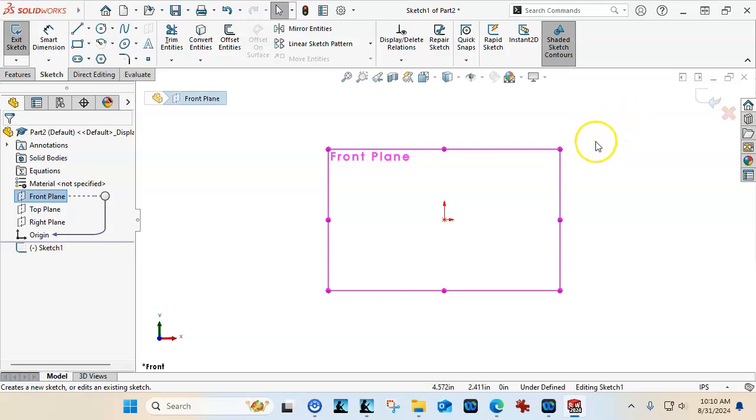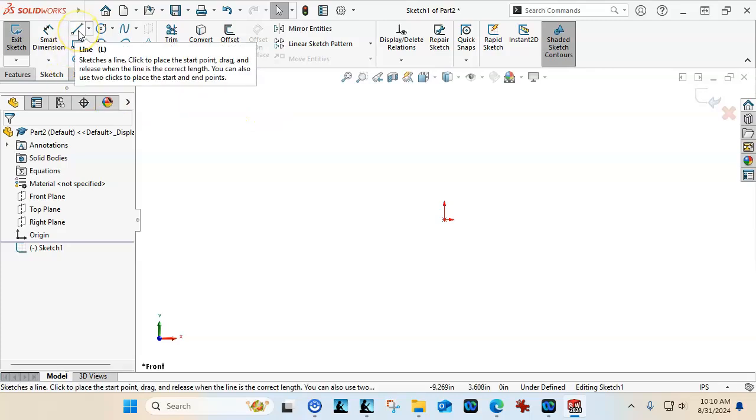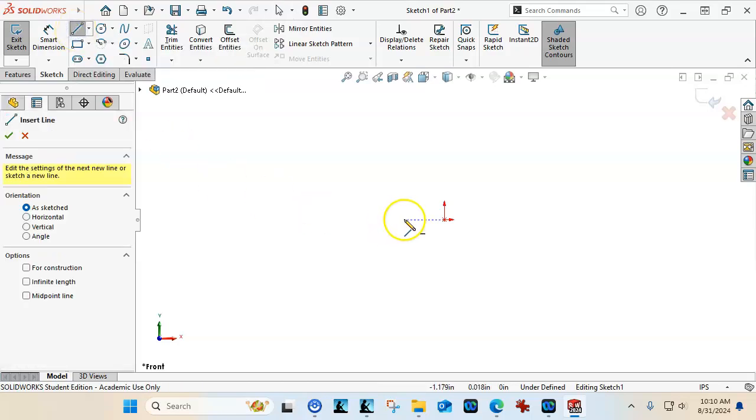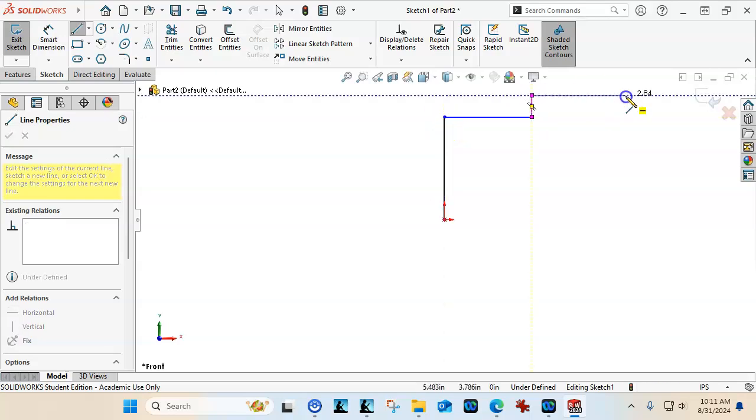As we go into chapter 3 and we start doing more complicated geometry or get a little more involved, then we'll want to make some decisions about the top plane or utilizing the right plane. Okay, so if we just go into the sketch, we could do a rectangle for the envelope, but I think I want to just go ahead and do the sketch. I'm not going to worry about the corner fillets, inside, outside fillets and rounds. So that's about 3 inches over, up. And again, I'm doing the click drag, that is my preference.